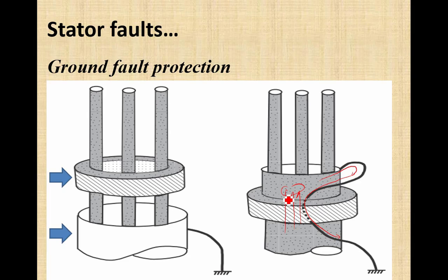So now the net sum which is producing flux in this flux summing CT is these three currents, IA plus IB plus IC, plus the neutral current in the sheath, and then we have passed the conductor back, so that will be plus and minus I neutral current, so that will be equal to 3 times the zero sequence current.